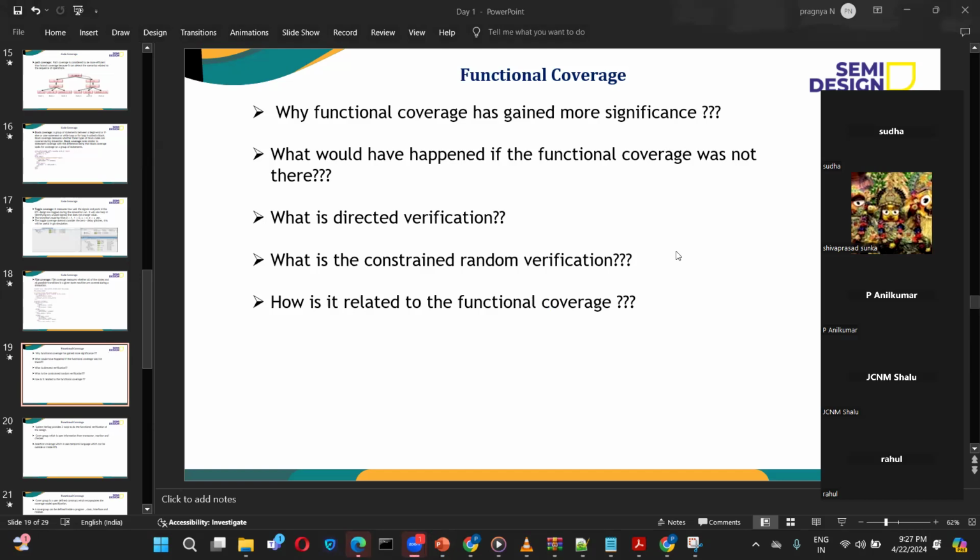The other way is, for example, everything is proper, meaning from the design side it is also saying that it should be covered. Everything has to be done. In that case, you have to go to your test bench or the stimulus. You need to improve your stimulus and make sure that that particular piece of code is getting covered. For example, you didn't create a stimulus at all.